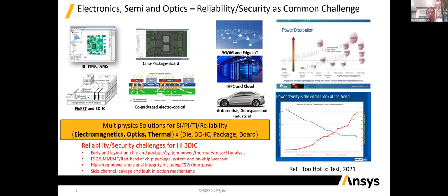In terms of 3D IC, there are several applications that we can see. For 5G and 6G design, there's analog and mixed signal design combined with digital processing. For example, people are looking at gallium nitride combined with a digital process. So we'll see that there's a high frequency demand for that kind of design. You can see a lot of that coming from ISSCC this week.